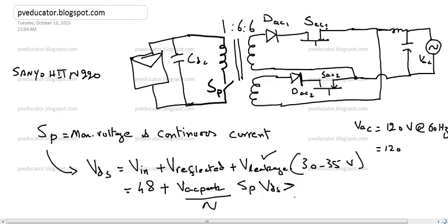And now the second thing is this continuous current, because this MOSFET has to bear the current that flows through this path. So this continuous current, now we have to calculate this one. In order to calculate this continuous current, one thing we should know about this SP current is that the control scheme of this SP is such that the current will have a sinusoidal envelope like this.